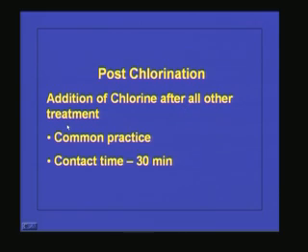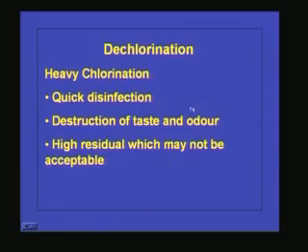Now, the other one is postchlorination. That means addition of chlorine after all other treatment. This is the most commonly practiced one. After the filtration, or after the end of all the treatment units, to whatever clean water is coming, we add the chlorine and allow it to stand for 30 minutes, because the usual contact time given in a chlorination unit is 30 minutes. At that time, whatever microorganisms are present will get killed. That is known as postchlorination. This is the most commonly practiced one.